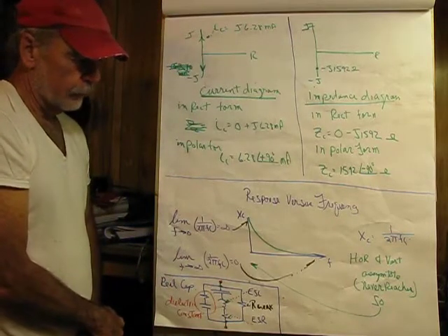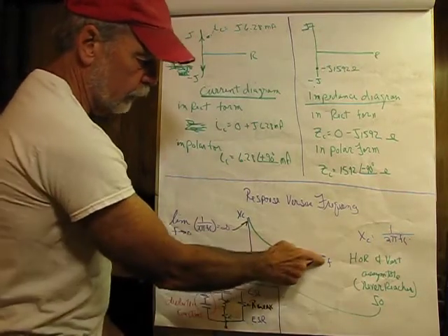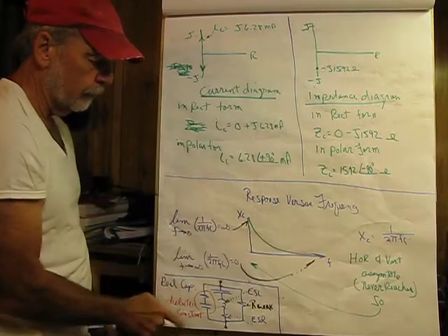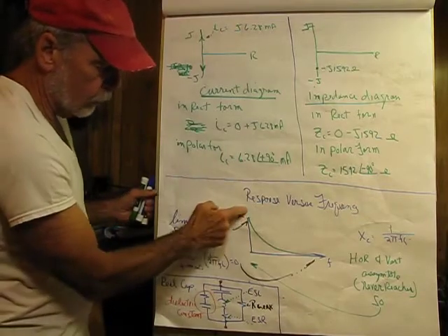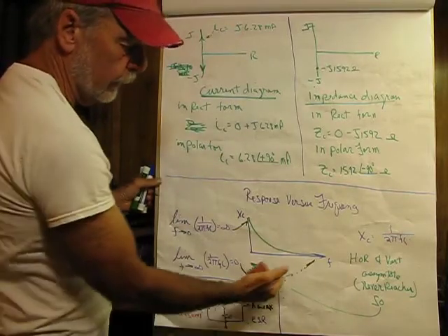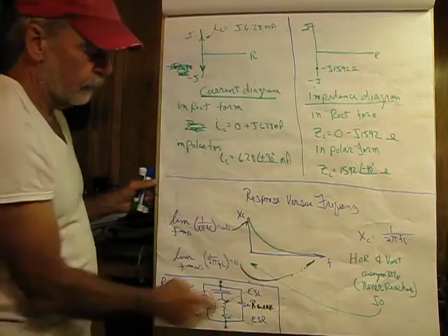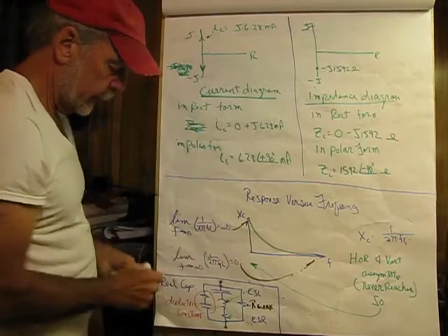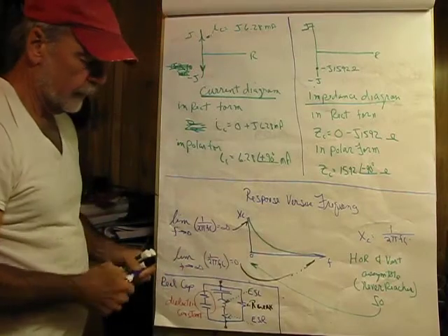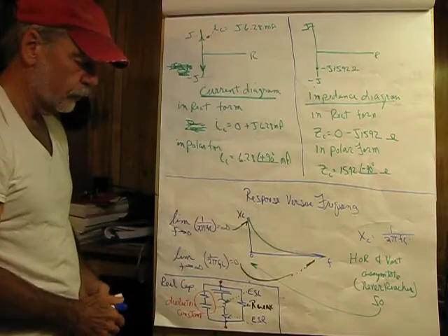Finally, let's take a look at the frequency response of the capacitive reactance. So f is going to be the abscissa, and the capacitive reactance is the ordinate. If we were to plot this out, what we would see is we would have two asymptotes. What an asymptote means, and this would be a horizontal asymptote, is approaches but never touches. And a vertical asymptote in the same way, and this here would be 0 frequency right there, means that the capacitive reactance approaches infinity but never quite gets to it.